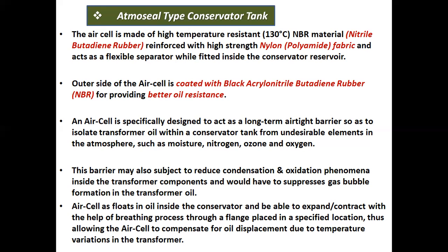The air cell floats in oil inside the conservator and is able to expand or contract with the help of the breathing process through a flange placed in a specified location, thus allowing the air cell to compensate for oil displacement due to temperature variations in the transformer.